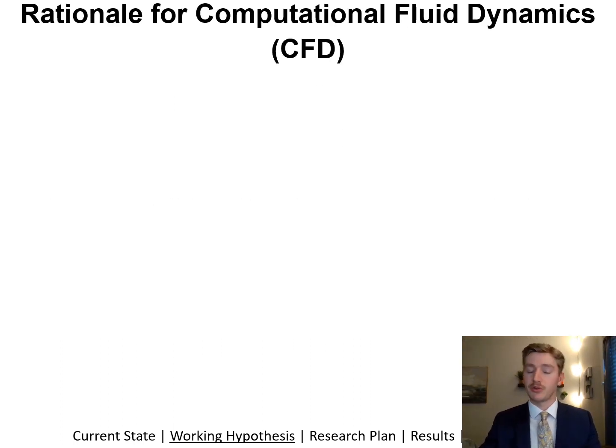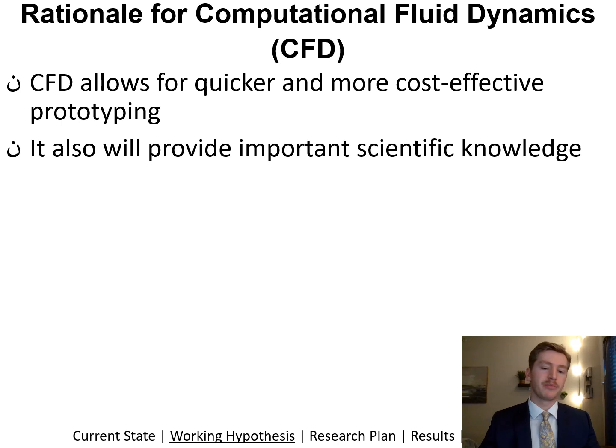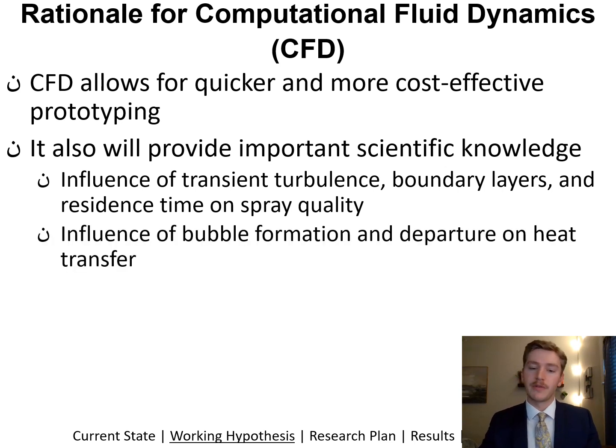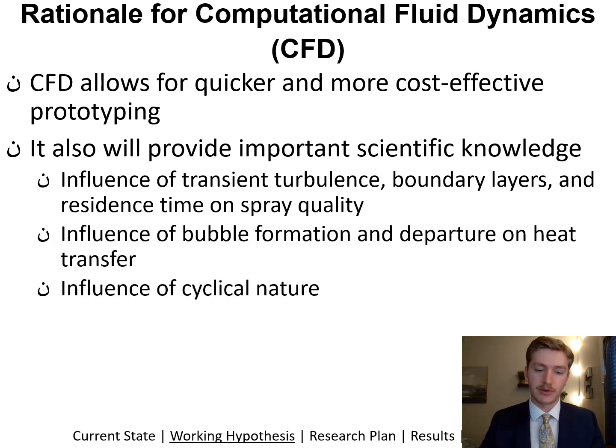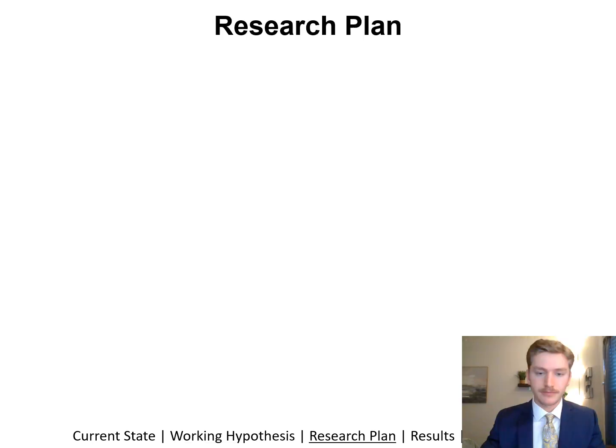Computational fluid dynamics, or CFD, is a very important tool in research and development because it allows for quicker and more cost-effective prototyping, and will also provide important scientific knowledge about the physical mechanisms at play in this device, particularly the influence of transient turbulence, boundary layers, and residence time on spray quality, the influence of bubble formation and departure on heat transfer, and the influence of the cyclical nature of this device. However, the risks of CFD necessitate verification of results.